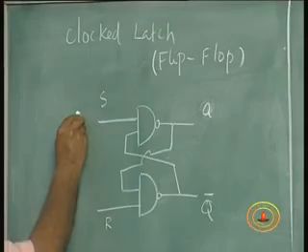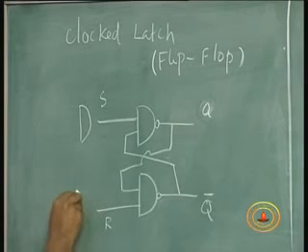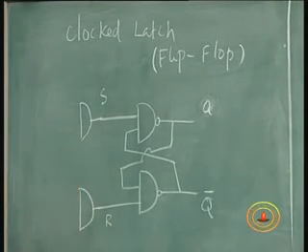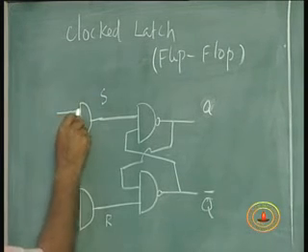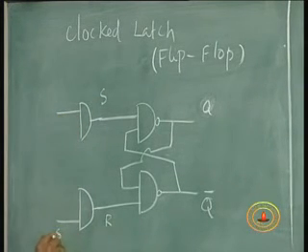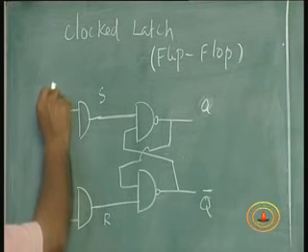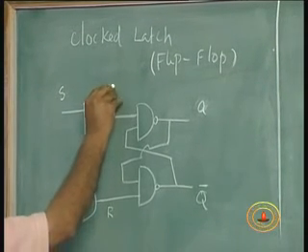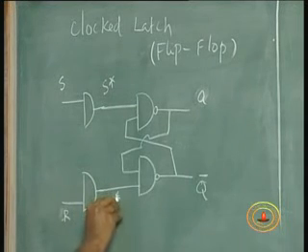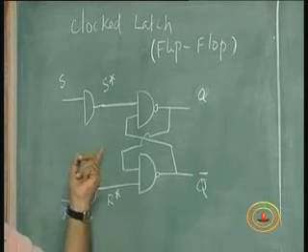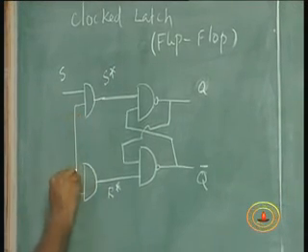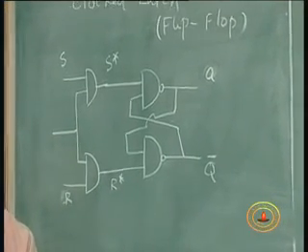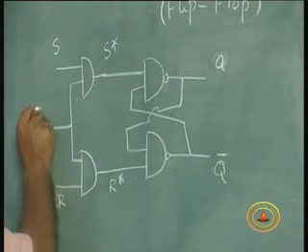It will remain as a memory state. So a very simple way of doing it is to put an AND gate in each of these, and instead of giving S and R directly, I can give S and R here, in these two places, and if you want to call this S star or R star, it's a gated output. And the second input to this will come from a signal which is called a clock signal.